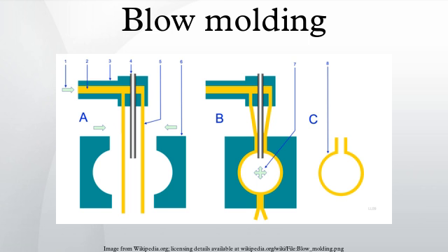When together they have large air gaps and small surface contact. By first stretching the molecules vertically then blowing to stretch horizontally, the biaxial stretching makes the molecules a cross shape. These crosses fit together leaving little space as more surface area is contacted, thus making the material less porous and increasing barrier strength against permeation. This process also increases the strength to be ideal for filling with carbonated drinks.